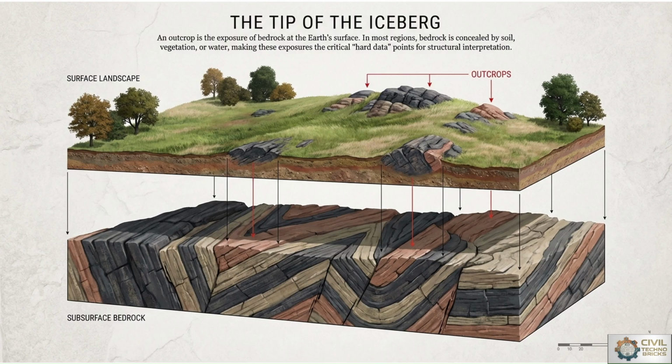In most regions, the rock formations are hidden below soil cover, vegetative material, and water bodies. So therefore, outcrops become valuable sources of geological information. Civil engineers and engineering geologists study these exposed rocks to understand the orientation, strength, weathering condition, and structural features of those rock masses which are on the surface of the earth, just like outcrops shown in image 1. Outcrop observation helps in predicting underground geological conditions for construction projects. With reference to this information, it is important to plan the construction of dam, highway, bridges, tunnels, and foundation system with the help of outcrops.